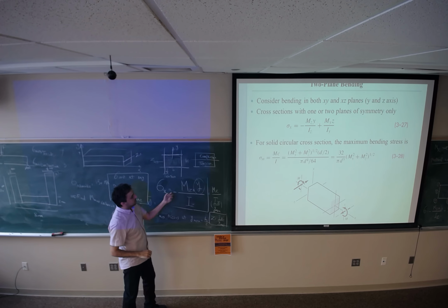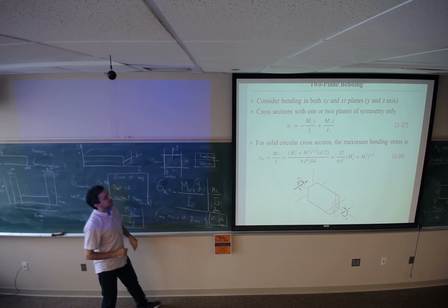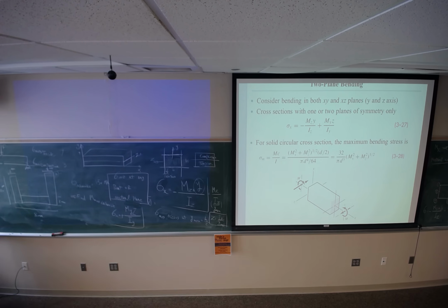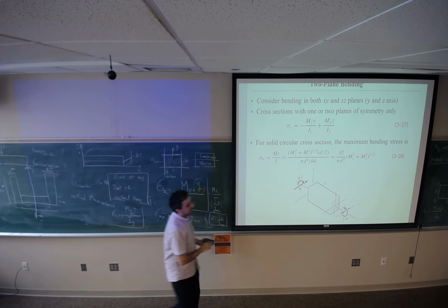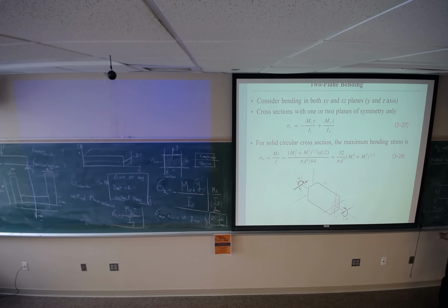The maximum normal stress occurs at the greatest distance from the centroidal, neutral axis. But where is the neutral axis? The y-axis is going to be here because we have symmetry, but for the z-axis, we don't know where to put the neutral axis. So we need to calculate that, based on the sigma equation that I wrote at the beginning.